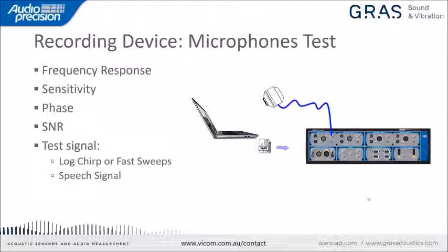And just as we mentioned before, we can use both logarithmic sine sweeps or fast step sweeps for these signals. But we can also use speech signals or music signals. And the APX 500 software can use speech or music signals to obtain a transfer function of the DUT. So this way, we can still perform acoustical measurements in devices that have issues passing sine signals through.